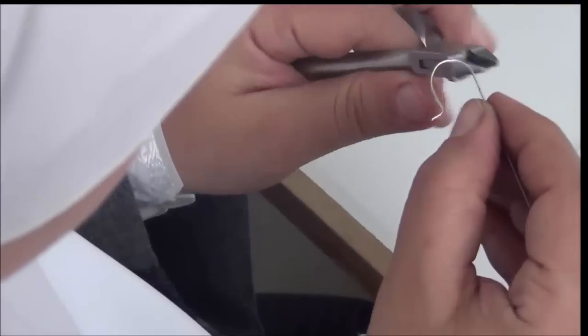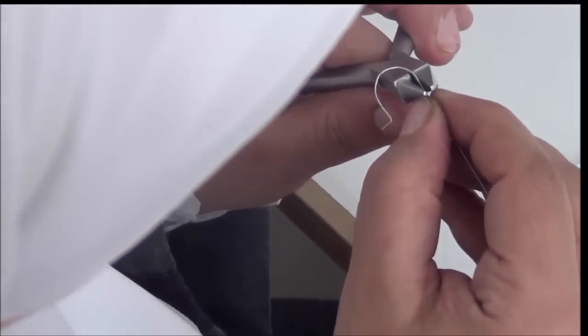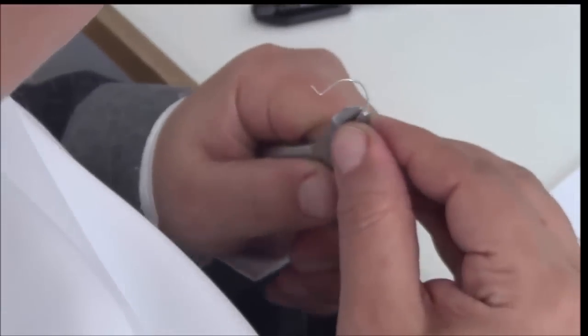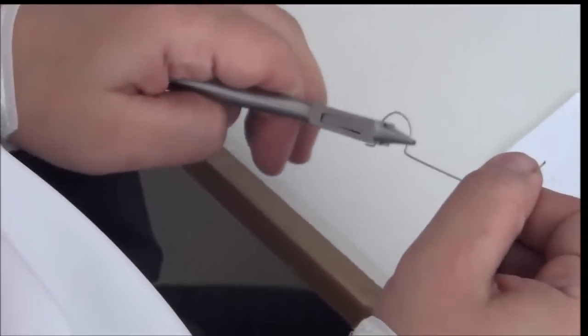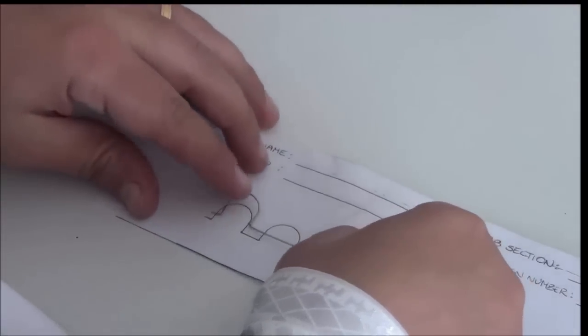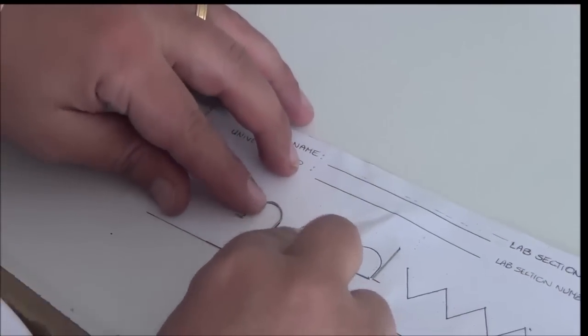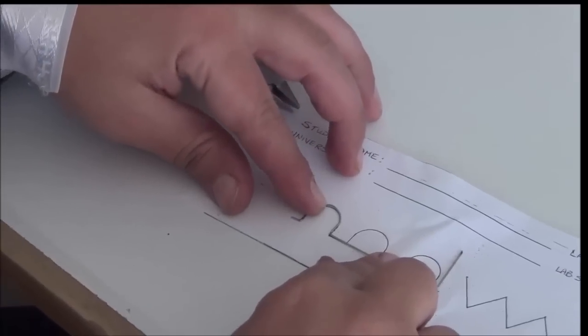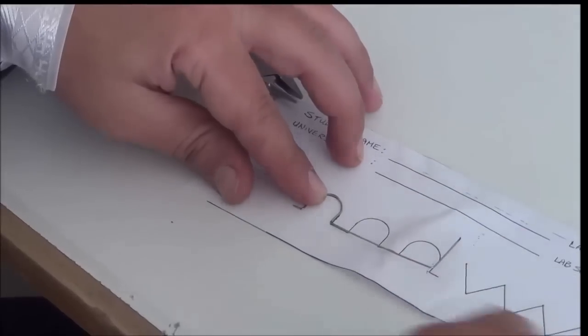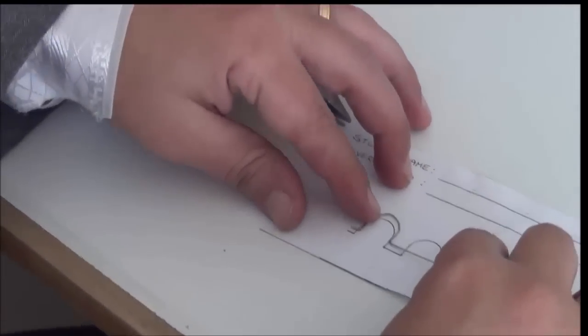Now because I want to bend an angle, I put the mark on the pegs, the straight angle peg, and then bend away with 90 degrees. And then make sure that everything is oriented flat with the paper. In case it's not flat, I go back and reorient it, and I continue my bending likewise. I continue putting another mark and bending, putting marks and bending until I reach the end of the figure. And then I also need to do this.